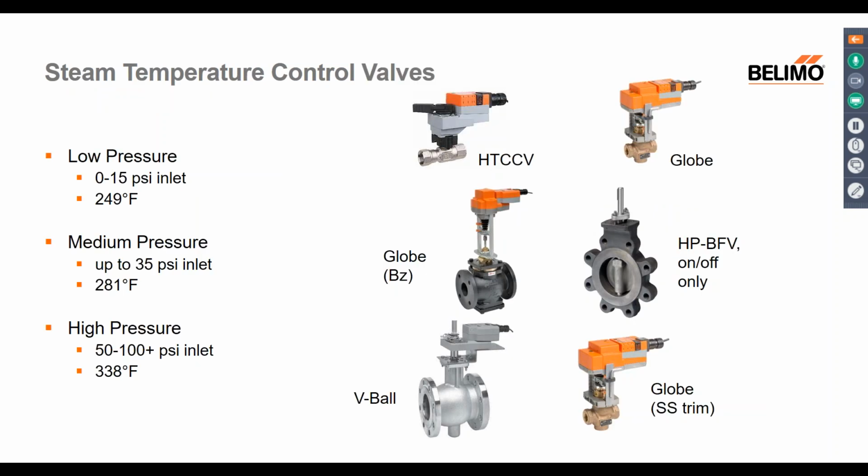Steam temperature control valves. What do we have for different applications? Now, you know, it's pursuant to what the engineer spec'd, or you talk to your customer, you talk to your end user, and they said, I have low pressure steam, fan coil units, and I need control valves. Well, for low pressure, 0 to 15 PSI, why I put 249 here, it's generally 250, I don't know, but again, that rule of thumb, 250,